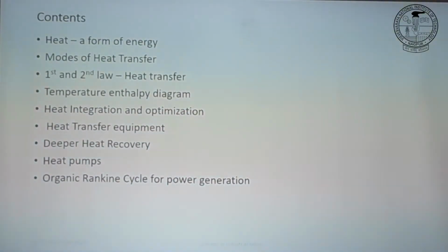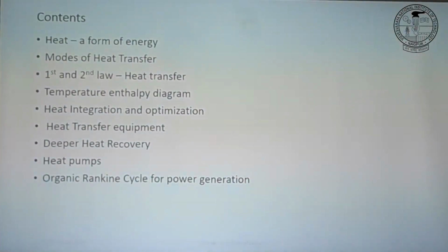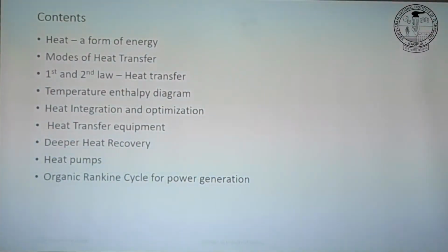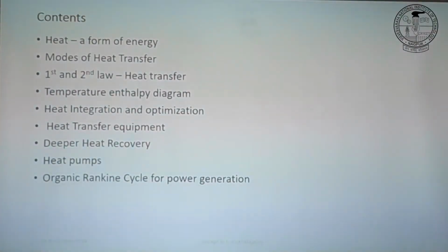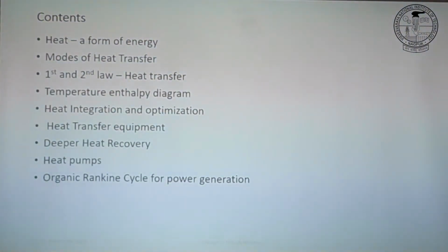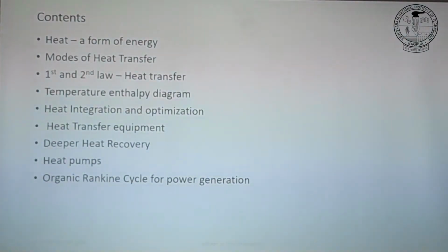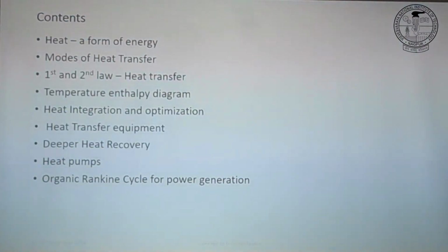Nowadays, there is a lot of pressure on energy recovery. So till now, in last 2 days, we talked about, if you remember, flue gas. We cool it up to 150, 160. We'll see today why only 150. Can we go a little bit deeper? Because actually 150 to 30 degrees, that's actually the energy lost to atmosphere. Can we still recover it? And at those low grade heat, if you can recover and generate electricity, so I'll explain a little bit more the Rankine cycle for power generation.